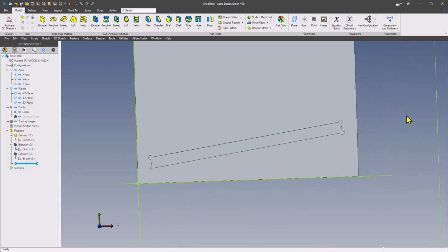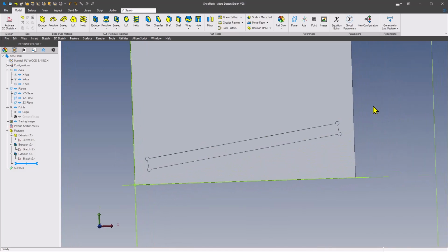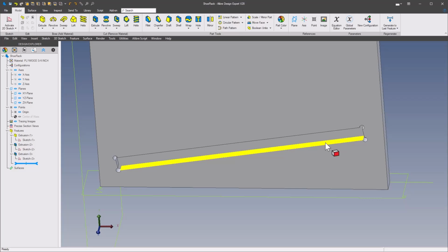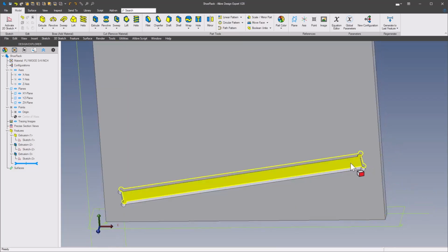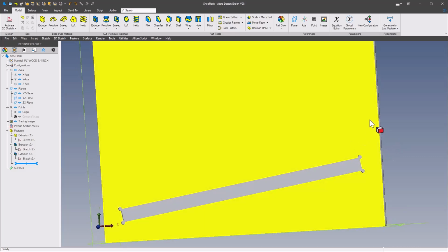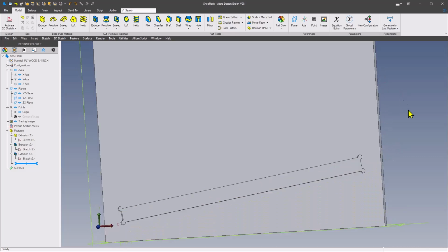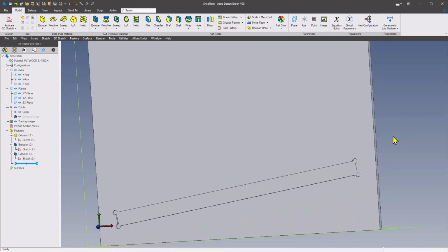The other thing I want to mention too is that there was a comment made that there's going to be a tolerance in here because, well, this slot being 3/4 of an inch, the plywood shelf in here may have a variance of between 3/4 and whatever the tolerance is going to be on the plywood, so it may not be exactly fit in here. So we're going to add a tolerance to these parts.